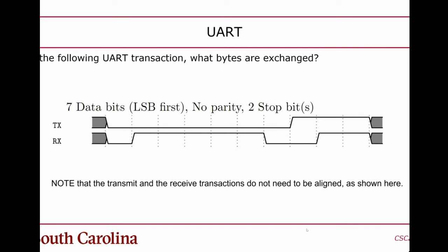Okay, so here's an example of a UART waveform, or kind of a timing diagram. Time flows from left to right. Each one of these traces is just showing 0 or 1, indicated by the line being on the bottom or the top of the trace row. I don't know what you call that actually. The line.